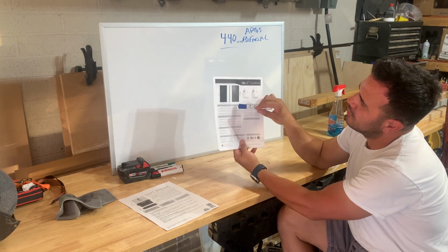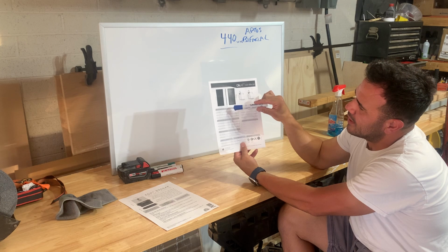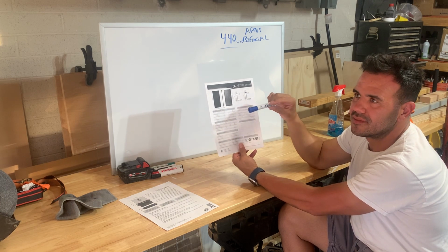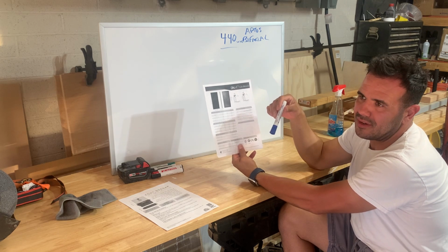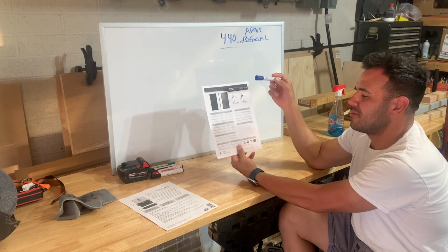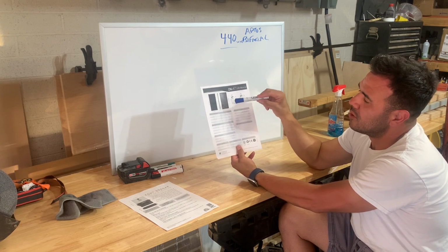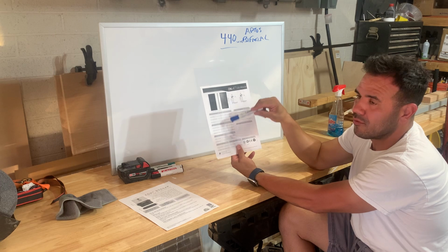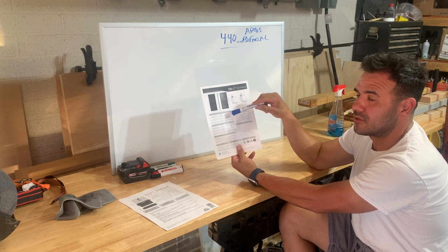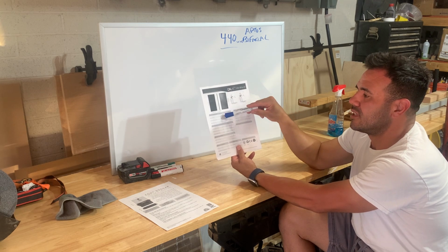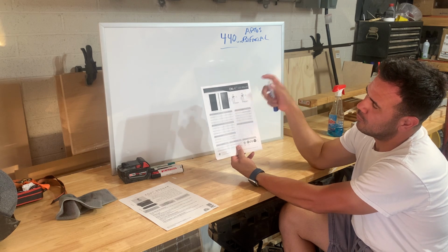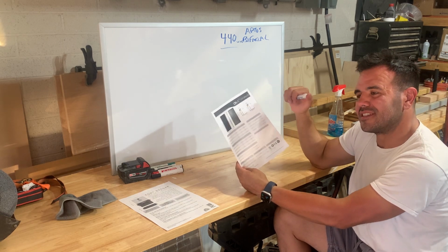All these figures on the electrical specification are measured in a laboratory under ideal conditions: the light hits the solar panel at the perfect angle, and the temperature is a perfect 77 degrees. I don't want to get hung up on temperature too much, but just know that the warmer the temperature is, the less efficient the panels are, and the colder the temperature is, the more efficient the panels can be. So your voltage can rise in colder temperatures, and in warmer temperatures, the voltage will decrease. But again, I don't want to get hung up on it because I just want to go over the basics.